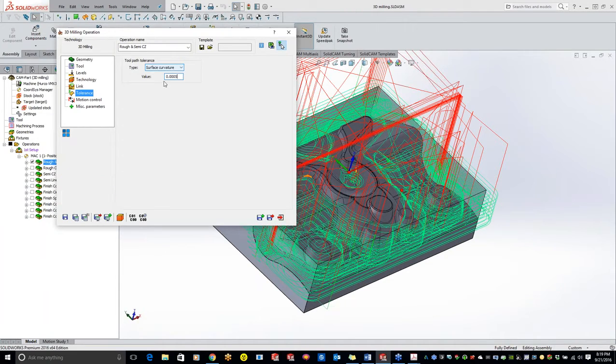Usually with the default, you can basically skip over this page and just get to link and skip the rest of it, but we'll definitely go through it. Now, motion control. If you want to do interpolation for distance, you can set that up. Rapid feed rates, you can set up also. Like I said, since 2007, since I've been using the software, I've never even touched this stuff in here. But if there is something in here that you need, approximate arc by lines, we can change that down. So instead of doing line segments, doing arcs, here's your tolerance for that.